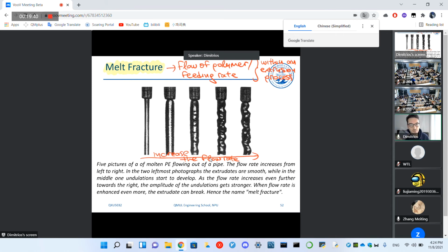So this is for a liquid, let's say, that is not affected by essentially how much is fed, because it does not display viscoelastic characteristics, okay? So the dimensions of the material that comes out from the die are the same as the dimensions of the die. Now, in the second figure, here we have this phenomenon that we said already is the die swell or Barus effect.